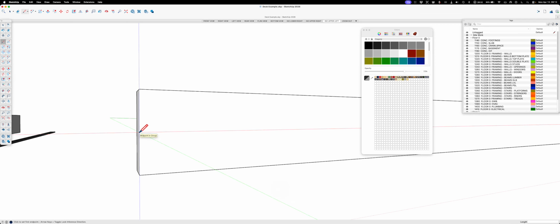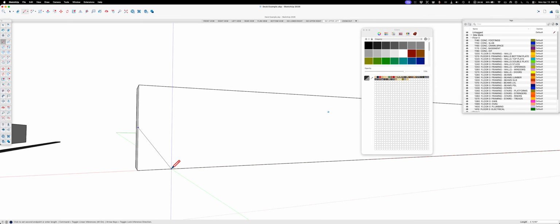I'll sometimes come over here with a line, find the middle, start drawing it on the face, and then there's 45 if you want a 45. So let's do this. Let's do T. So there's the middle. And then I'm using these temporary guides. Let's say you wanted to come over, what is this, 2 inches? Then you would do a line from there to there.